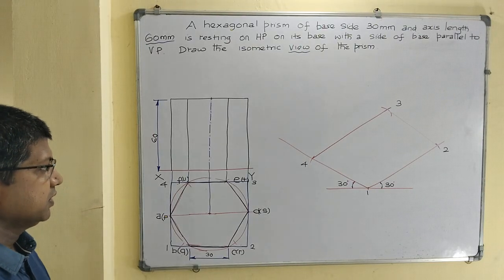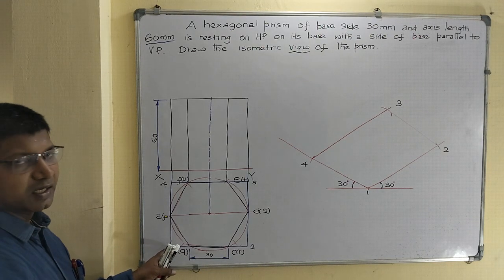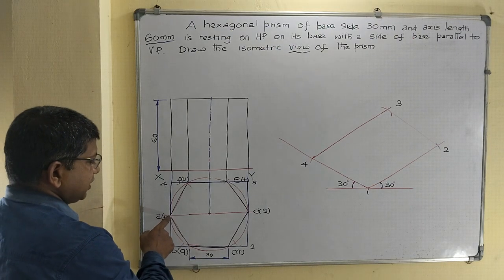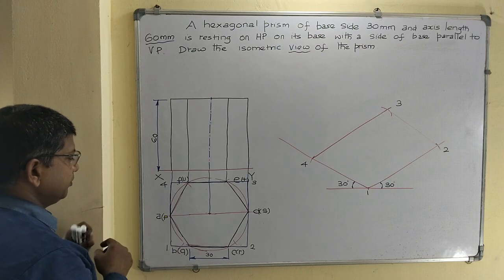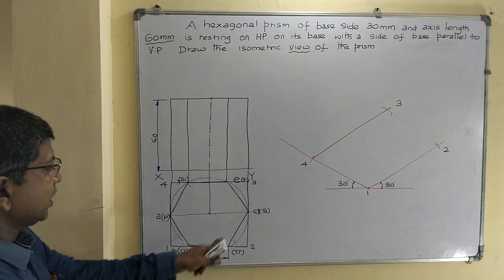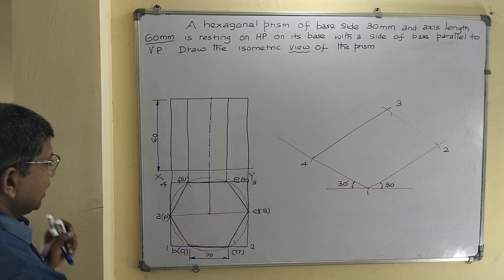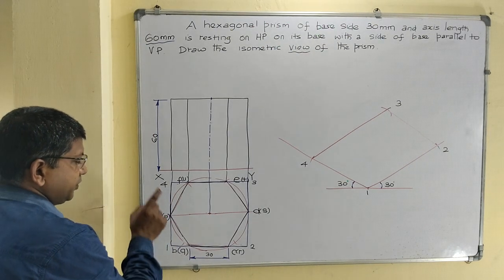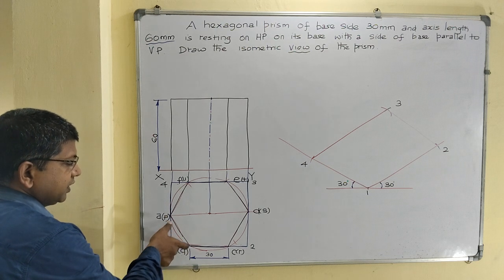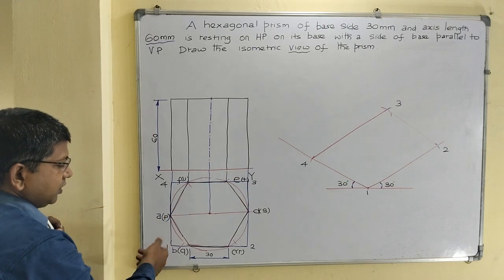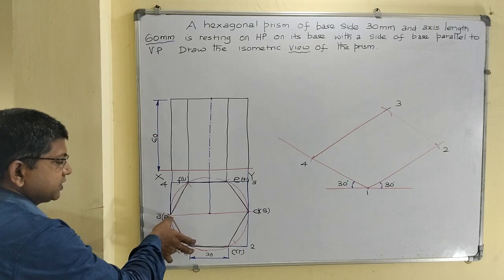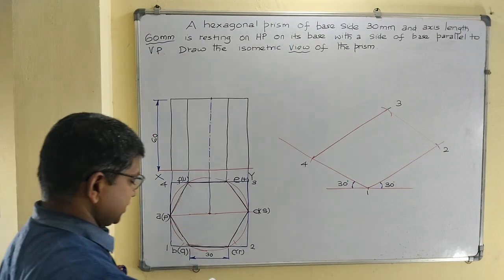How to draw the base hexagon? From any one corner as the reference point, for example, now draw the base point P on PQRSTU. How to draw the point P? Mark the point P. Take the nearest corner point as reference point. Take the distance as radius. With point 1 as center, by using compass, take the distance to point P as radius and draw the arc.